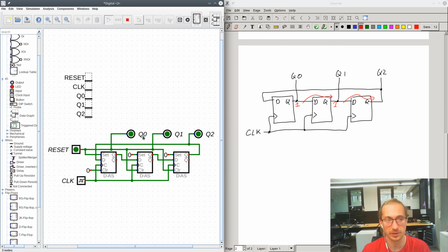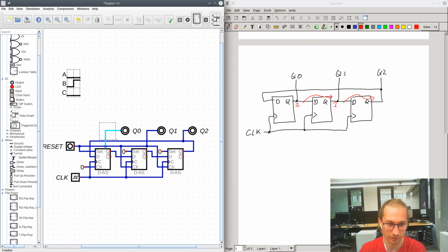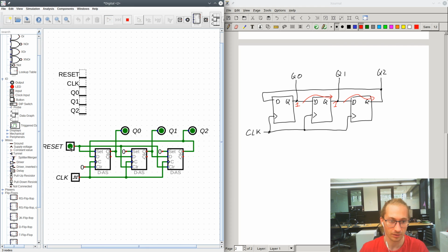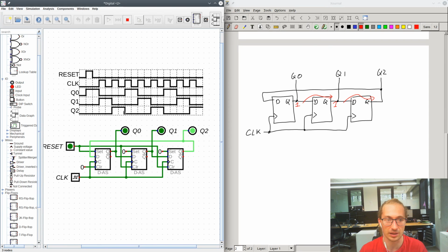So when we start the simulation, the flip-flops will start at 0, so we can use the reset line to asynchronously set the flip-flops, and there's a typo there, so that Q should connect to the output, and that Q1, that should connect to the output there. Yeah, that's better. So we hit the reset pin, we reset the circuit into a known configuration, and then by toggling the clock, the ring counter shifts the bit along, so each flip-flop moves the bit to the next, and we get the same intended behavior of our traffic light as earlier.